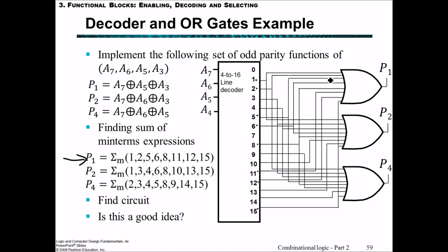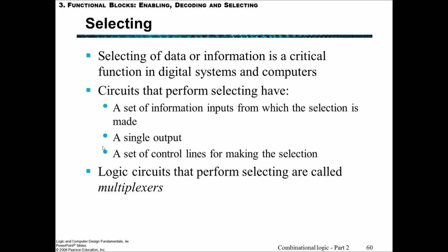So this is the circuit, and the question is, is this a good idea? And clearly, it's a bit of a mess because the complexity is really too high. It'd be much better to implement the functions with the XOR gates as it was originally specified. Also, something else that's not obvious here is that the sharing of the logic can cause 2 bits to be an error, which for this application is really not detectable. This is called a Hamming encoder, and you can read in the textbook for more information about that. Note also that even though it would be better to use the XOR gates, we really shouldn't share those in the implementation either.